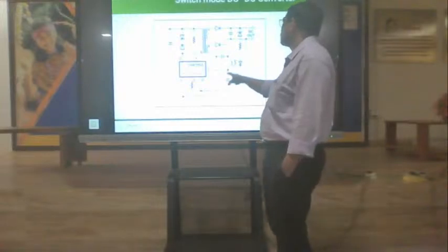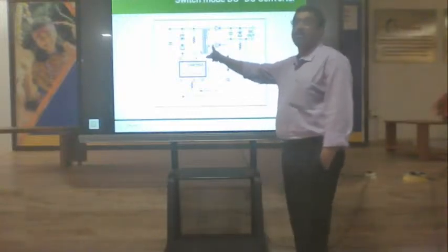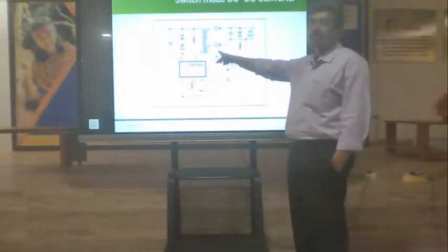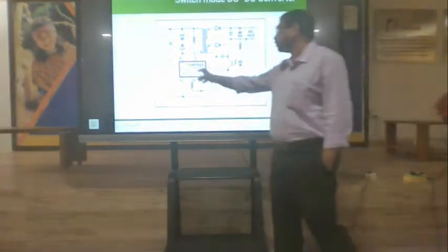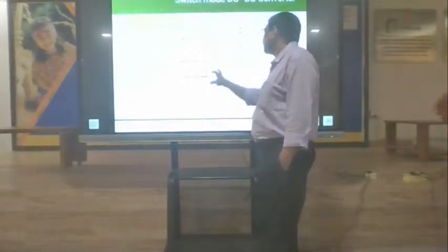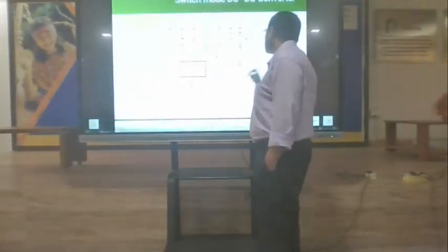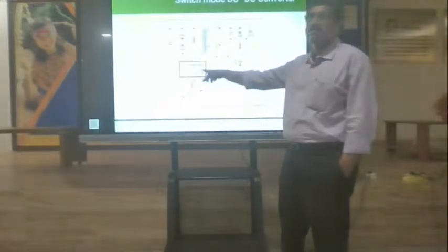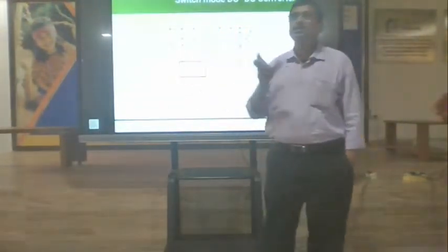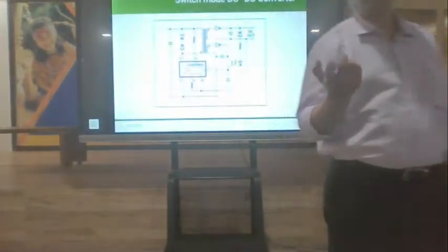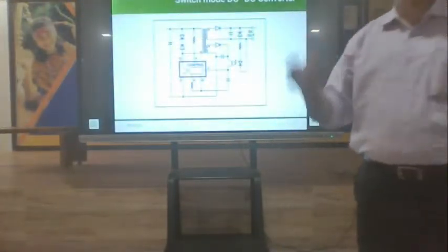So the current is set by the inductance of this feedback winding. Once there is a flow in this, there will be a program control within this controller. If there is current flow in this C pin, the control pin, what will happen immediately? The duty cycle of this is going to decrease, like say the on time is going to decrease.